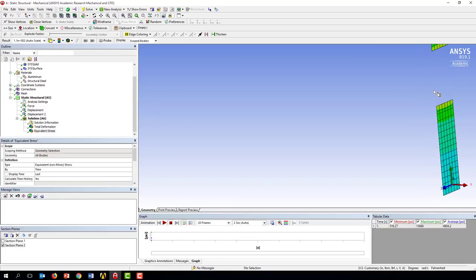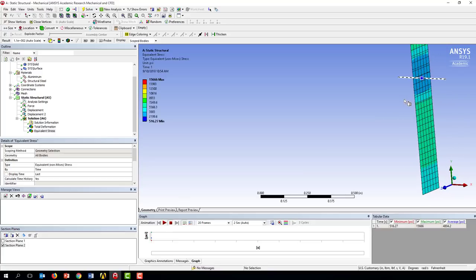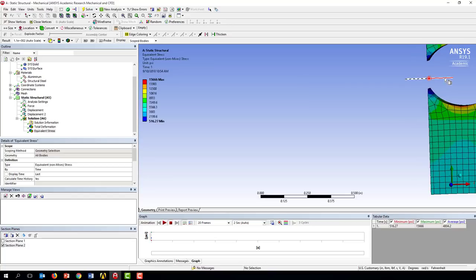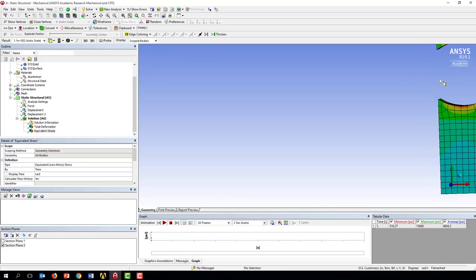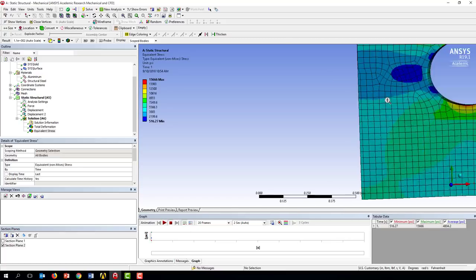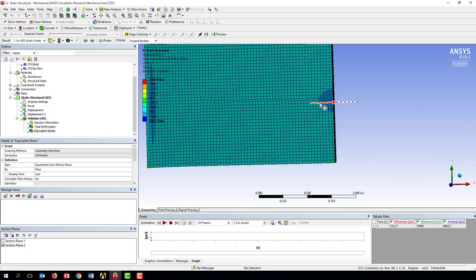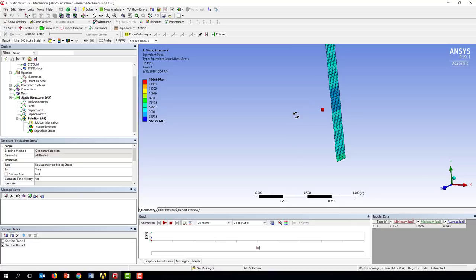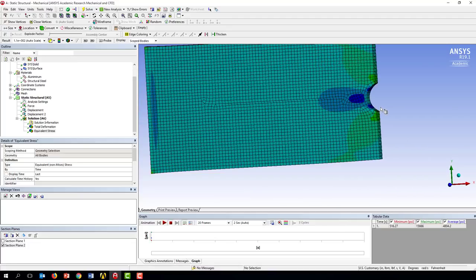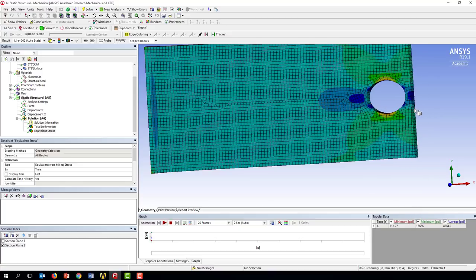You see there's brick type elements, and the stresses are pretty uniform. The shapes are nice and straight. That's one of the advantages of these, is it makes for uniform shapes. If I click on one side, it's toggling whether it's showing just a plane or that side. I can click on here and drag it back and forth. Right, and if I want to click on the other side, I can click over here. I double click, it just shows me an individual layer. So I can scan through there and see there. And it's fairly uniform, and it's a pretty good looking mesh arrangement. And it does take a pretty fine mesh in order to get a good resolution around this with the brick elements.